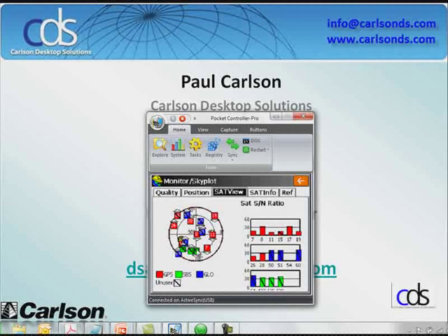Now, I'm connected to the network. My GPS receiver is GLONASS capable. Why am I not getting those GLONASS? Well, in order to receive GLONASS, both the base and the rover have to be able to receive that GLONASS satellite data. In this case, the base I'm connected to on the network is not GLONASS capable. So because my receiver is, if that base is not, I will not take advantage or get to use those